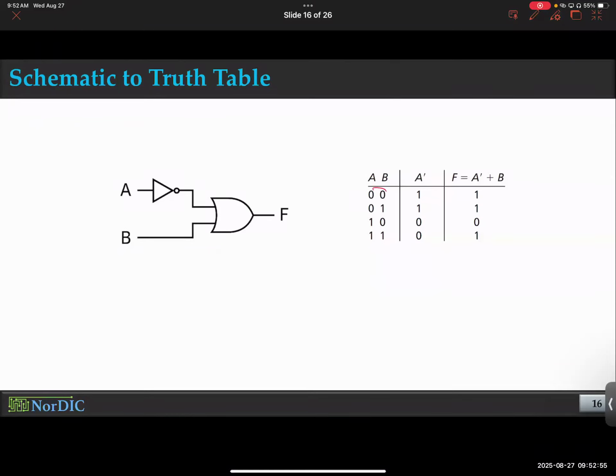Here is how. You could just keep plugging in these numbers, identify the inputs, put in all the combinations, and see how the output behaves in the hardware testing phase. Okay? And hardware, don't give up. Are you still with me? Okay. How many outputs do you have? Tell me. One. Just one output. So probe, it's like people have probe stations where they can connect different probes and measure the voltage at different nodes of the circuit. So just connect one probe at the output and notice how many inputs you have. Probe those inputs. If you have 10 inputs, 10 probes, 7 inputs, 7 probes.